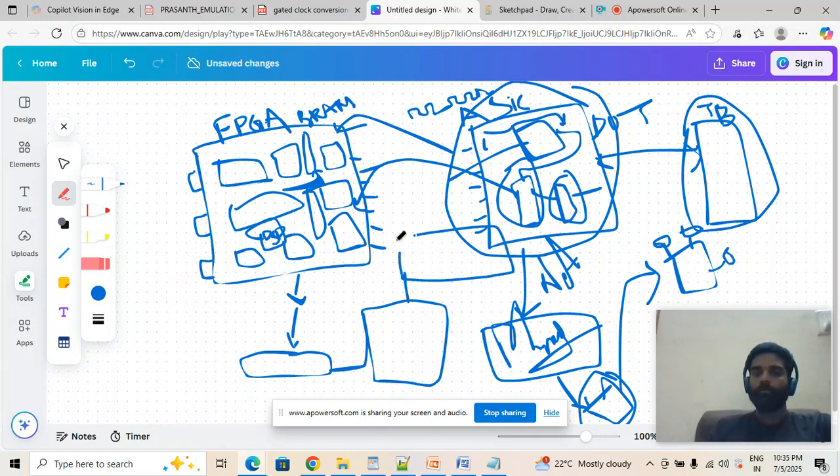You can just connect some real-time logic analyzer, where you can actually connect all your signals, similar to the simulation. Here we don't do the simulation point of view. We directly generate your netlist file. So this backend will do the place and route for the corresponding FPGAs, and it will give you the bitstream file.